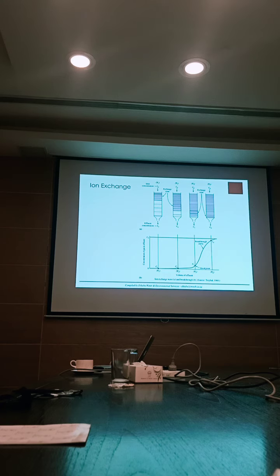Sorry, you were going to say something? Yeah, regenerate the resin. Yeah. So you've got to add a regenerant to the process to then return this back to this active resin media that you can reuse. So you can reuse the resin. It doesn't last forever. The company can come and fetch it and take it away and regenerate it for you and bring it back, depending on your appetite for operation.